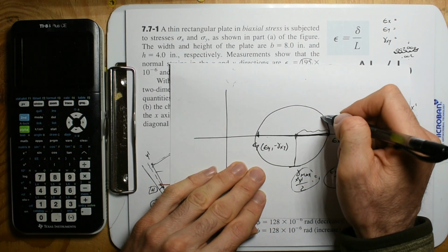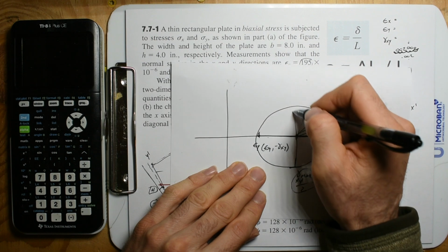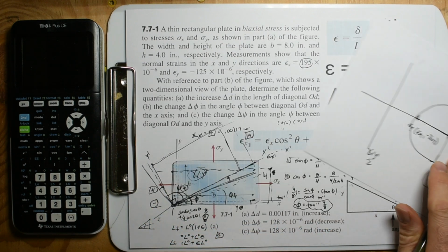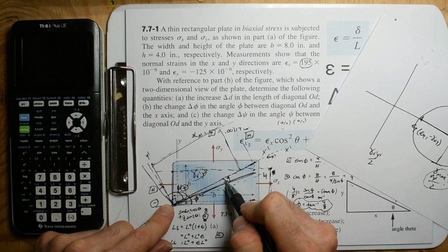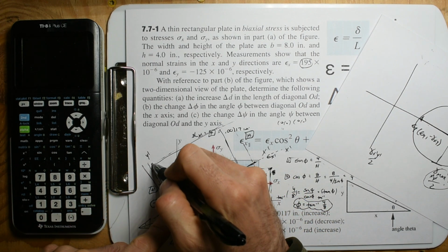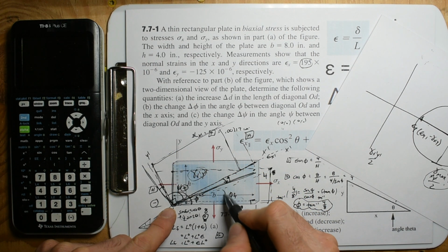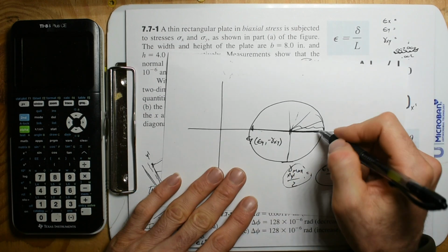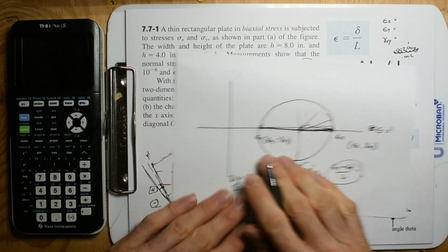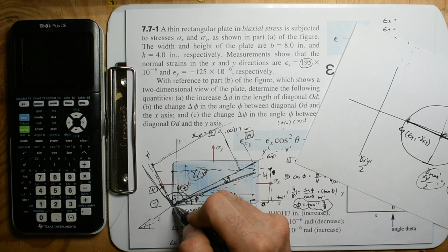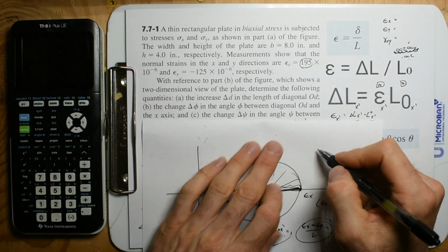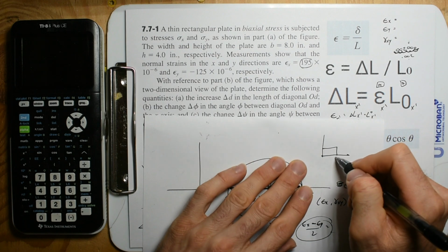So we can rotate this, and if we rotate it any amount, we're going to get shear. This angle went this way, and we're going to get negative shear. The only place that we get zero shear is when this angle is 0, or when you flip it and it's 180. So our little element is right there.